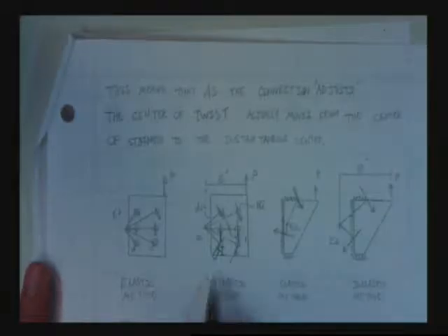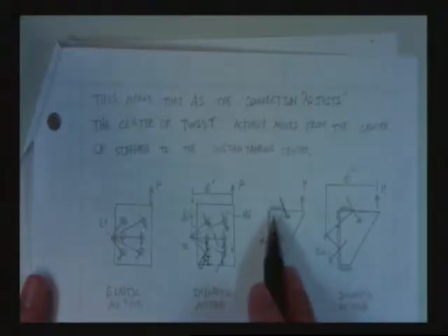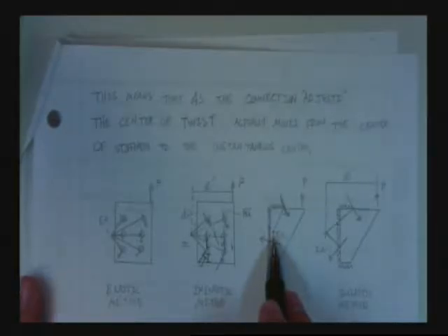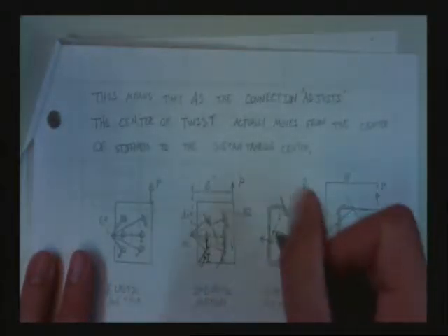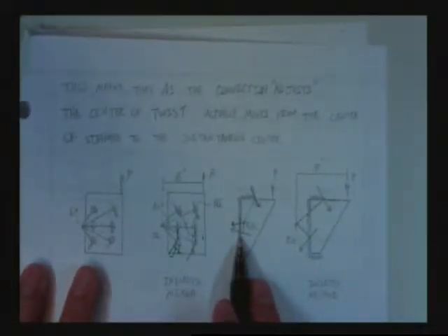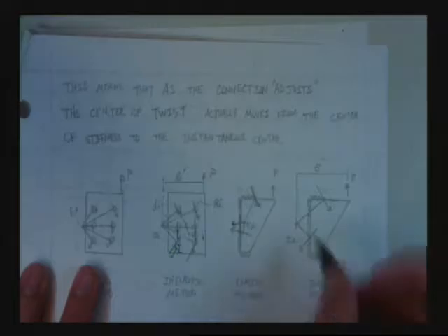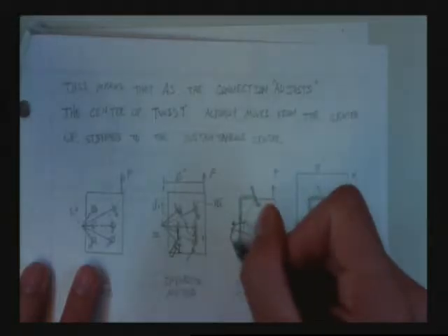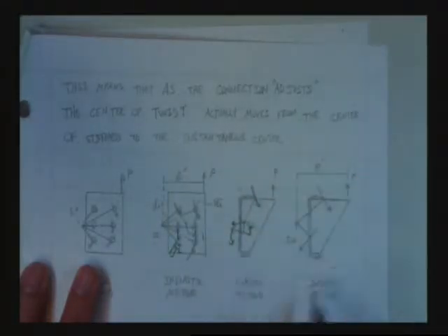Uniform bolt layout. Now, again, when we do something like welds, in this C-shaped case, sometimes your elastic center will be something like this, and this is very odd and strange for people: this elastic center can move, and it will move all the way out here. And this is strange. This weld, which you would think would be stressed in this direction, actually ends up with the force vectors rotating, and at failure they are out here. Really odd and strange.